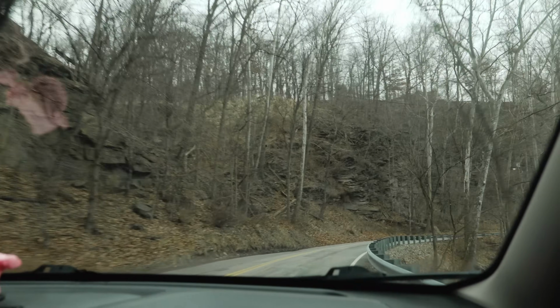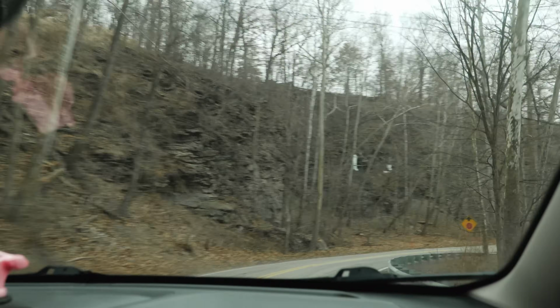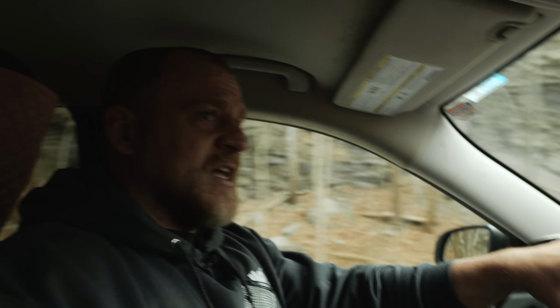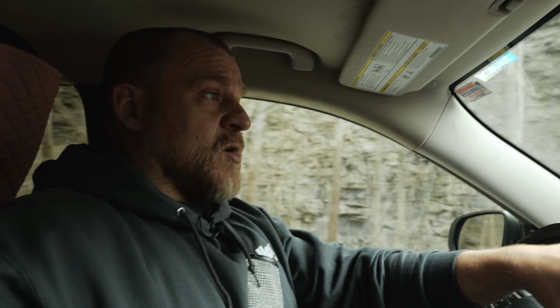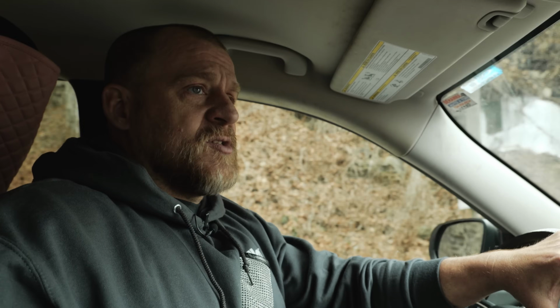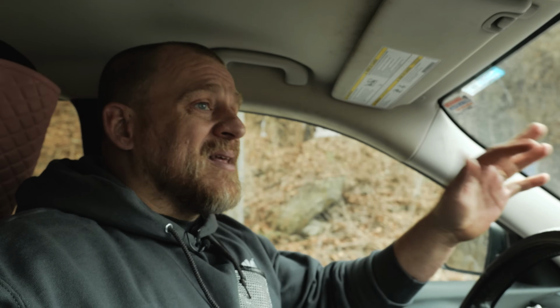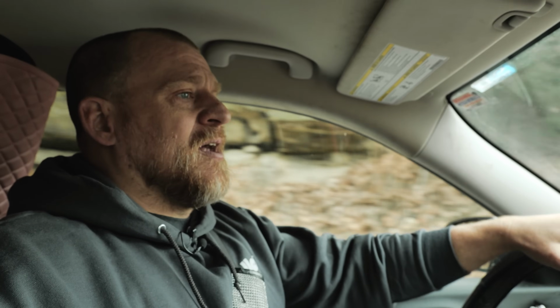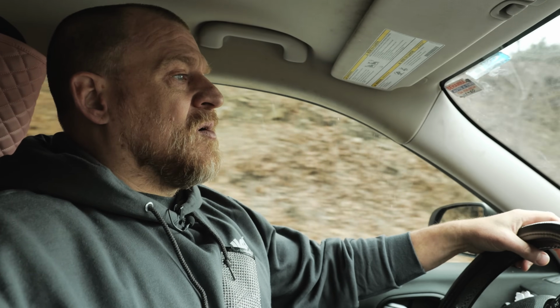When you would use that test is when you have fixed O2 signals, or when you don't know the range of the sensor that you're checking. A lot of these cars use widebands, and a wideband sensor reports in like the 4 milliamp range. 4 milliamps is a super tiny number, and they don't report that on the scan tool on a lot of cars.